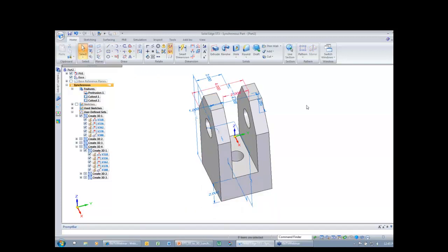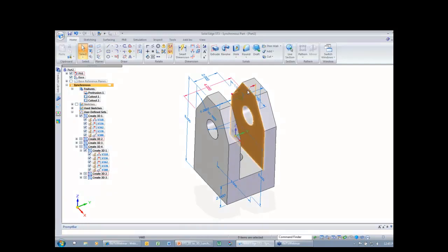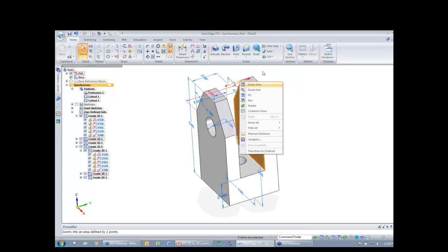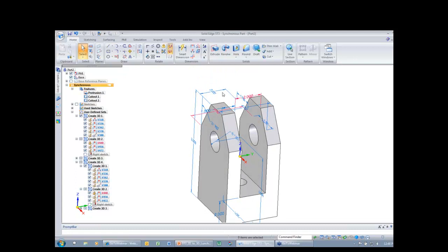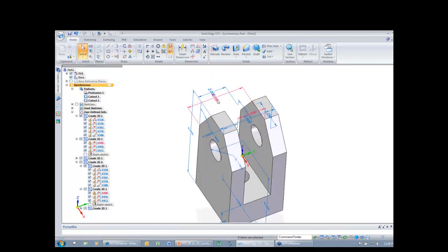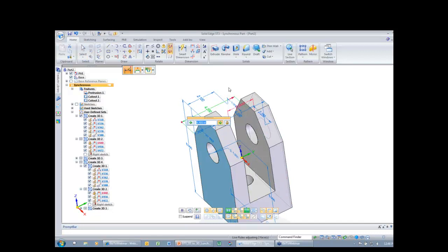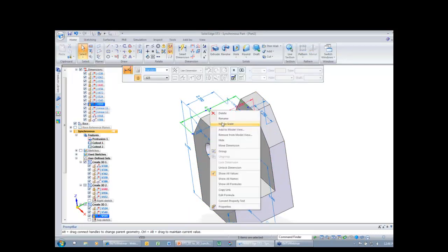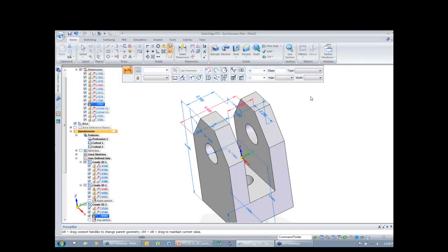I'm going to go ahead and lock this 4-inch dimension. I keep saying millimeters, I'm sorry, 4 inches there. And what I can do is set up a formula on this 2-inch dimension like we're used to. I can just right-click on it and say, let's edit a formula. And I already have that locked. So what you're going to see is that those are locked. And if I want to make a change to those, I can make that change and show you where the edit formula is. My screen wasn't updating, but I can say edit formula and set that to be half as much.